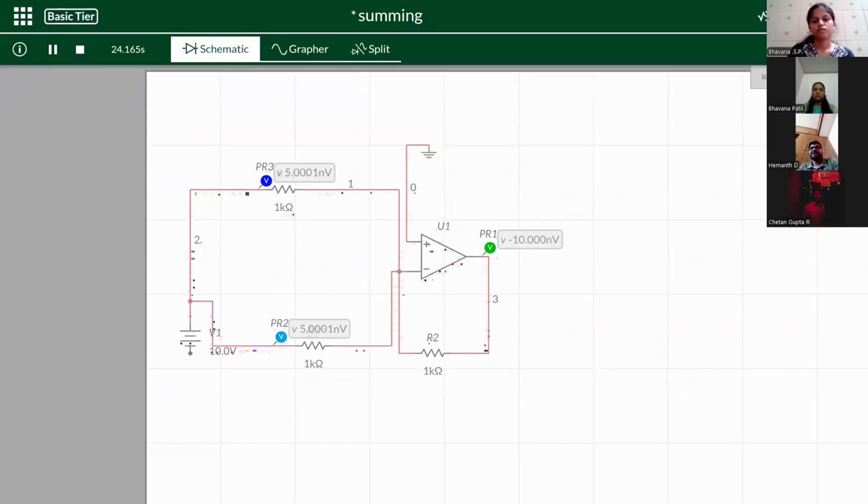Applications of this circuit are analog sensor signal conditioning where interference must be rejected, audio electronics to eliminate hum and noise picked up by cables, and data acquisition systems that require precision amplification of small differential signals while ignoring the noise. To conclude this topic, the simulated differential amplifier circuit demonstrates the principle of common mode rejection, producing almost zero output when both inputs were equal, which confirms correct design and theoretical operation.